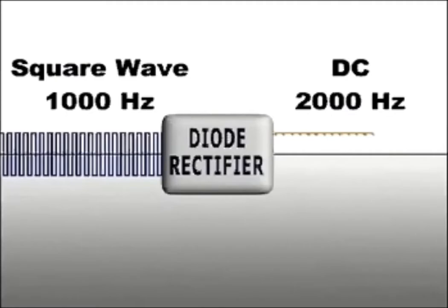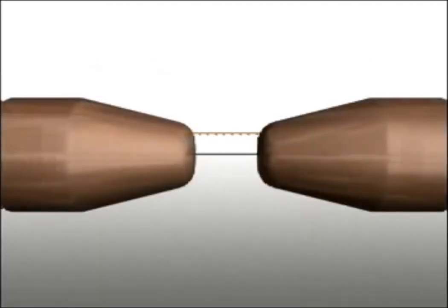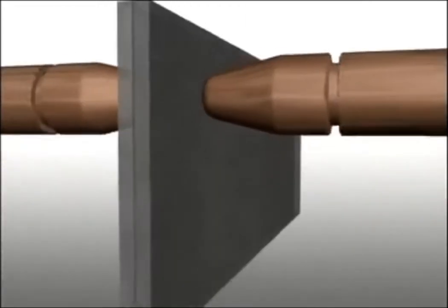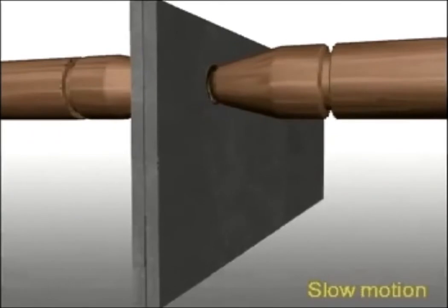The output waveform produced by the ProSpot PR2000 is perfect for resistance spot welding. As you can see in the slow motion, the current delivery is perfectly smooth. Another advantage with the inverter technology is that the current drawn from the body shop voltage source is reduced, which provides a surplus of power to other equipment in the shop. Old non-inverter DC technology would not allow this.